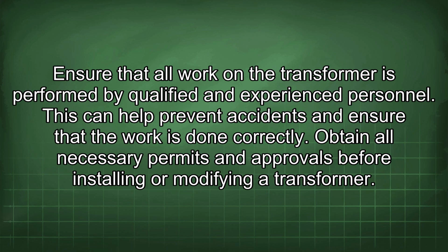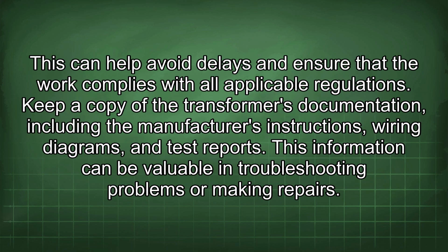Obtain all necessary permits and approvals before installing or modifying a transformer. This can help avoid delays and ensure that the work complies with all applicable regulations. Keep a copy of the transformer's documentation, including the manufacturer's instructions, wiring diagrams, and test reports. This information can be valuable in troubleshooting problems or making repairs.